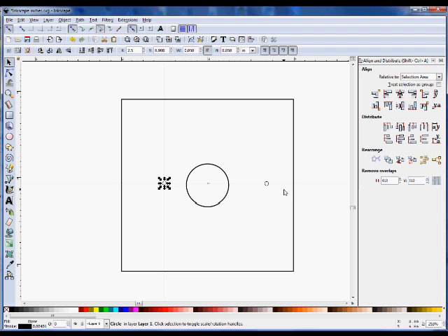Now this one over here, you want to have 1 inch in from this side, so that's going to be 3.5, or 1/2 inch in from the side, so you come up here and just change this to 3.5. So now basically you have them set up so that they're equal distant, or whatever distance you want over here. You can use these to position them.